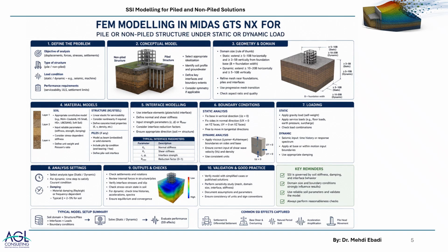If you want to go more in depth, then you should go to models like hardening soil, hardening soil small strain, and we can go deeper by selecting case-specific soil models depending on the requirements of each model and the materials involved. That's another category we just briefly refer to.